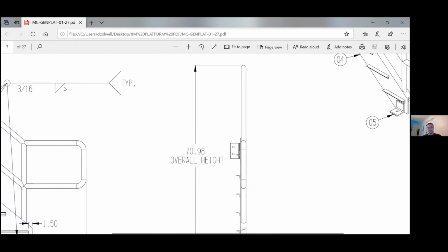This is a fillet weld. And I would have it on the bottom and on the top. And that would tell the manufacturer to weld both sides of the part. If for some reason I can't get an arrow over here to point to this side, I can just point to this side and put the information on top of the line, and that would mean weld the far side. So anything on the bottom is near side, meaning in reference to where the arrow is pointing. Anything on the top is far side.